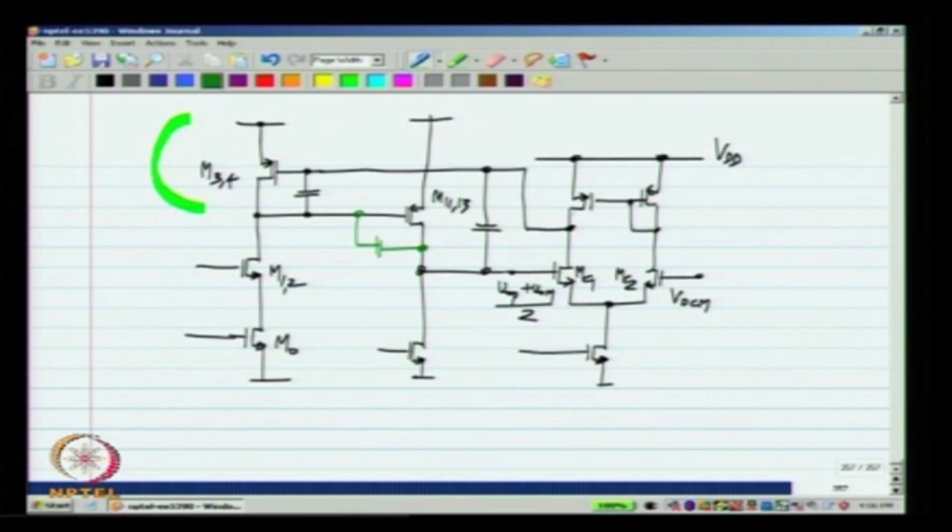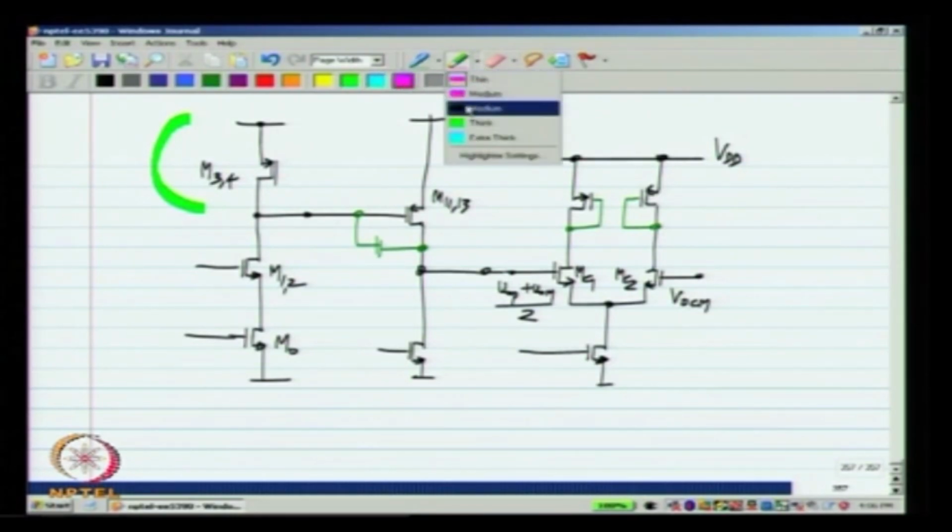So, what is normally done is not to use an op amp in this transconductor, but use some amplifier that has a positive incremental gain, and it is very easy to make a low gain amplifier. All that is done is to do this. Now, you know that diode connected transistors have an impedance of 1 by Gm. Now, this is like a differential pair loaded by 2 resistors whose value is 1 over Gm.